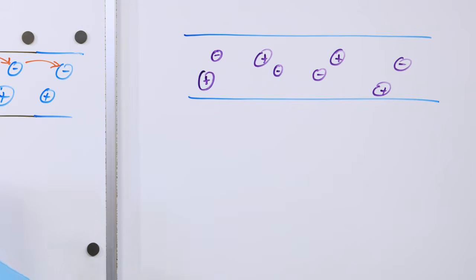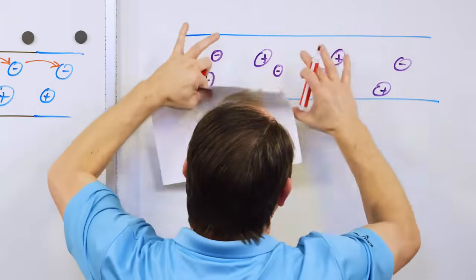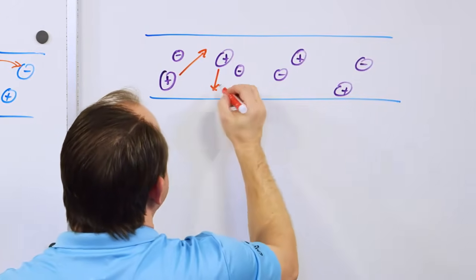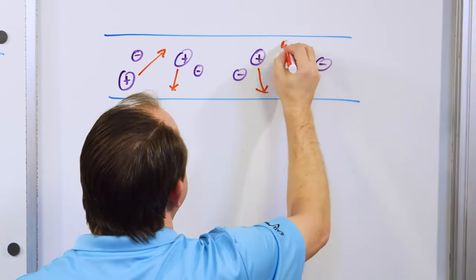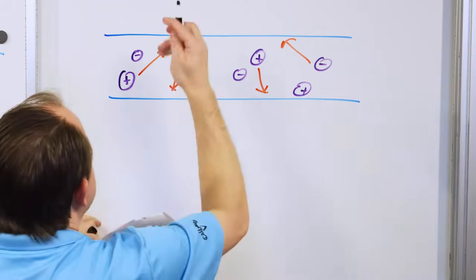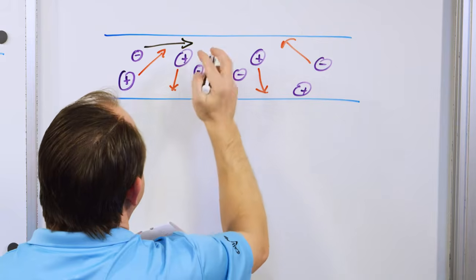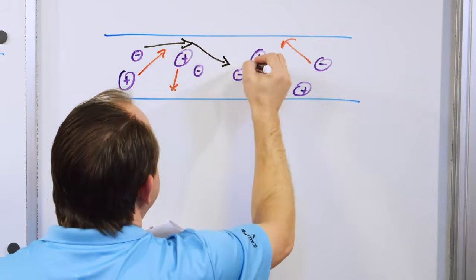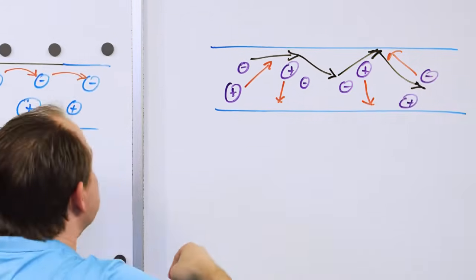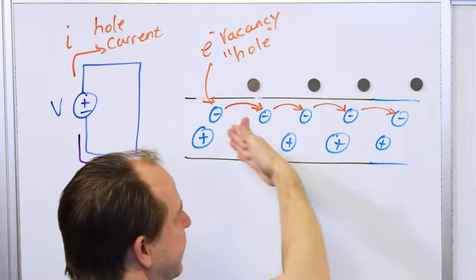But what's really happening here is this atom, because it's at a certain room temperature, is agitated. Everything's vibrating, even at room temperature. So this atom is moving this way, and this one is moving this way, and the electrons are jiggling too. So whenever this electron tries to hop to the next atom, it's going to scatter off one of these atoms and maybe ricochet. Then it's going to hit another atom at an angle and maybe ricochet. So it's not really a nice even hop with no resistance, just sailing right through.